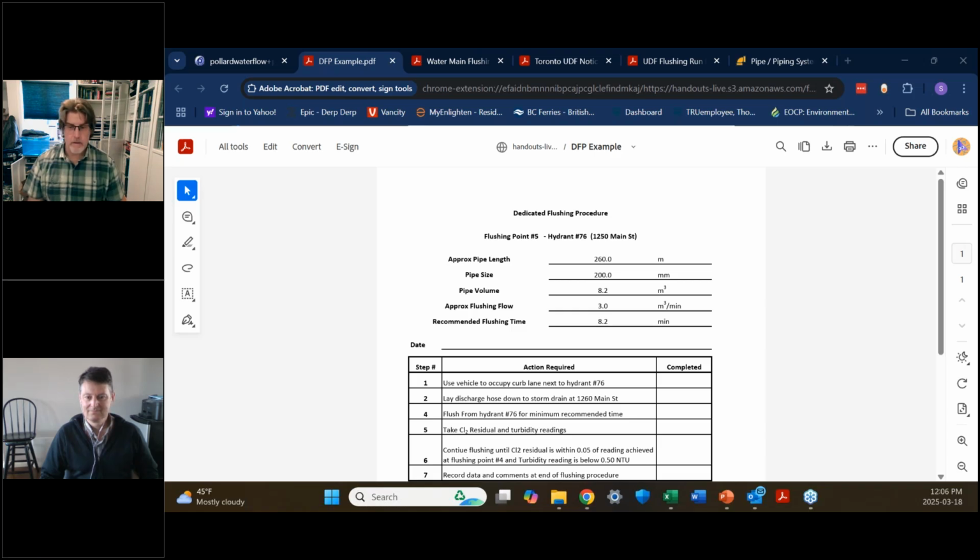Okay, he had another question. Thank you. Is it possible to effectively scour systems with smaller than 4-inch pipes? Any advice, residences? So I know my chart, I started it at 4-inch, and usually we try not to, or don't see a lot less than 4 inches for some systems. Obviously, they might have some 2-inch mains that are going out there. So you can still meet those scouring velocities in those 2-inch pipes. Yeah. That's good. Thank you.